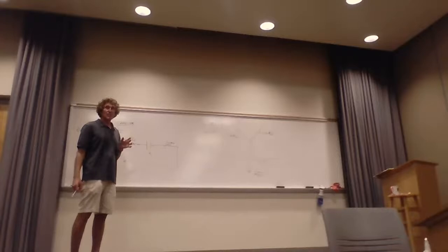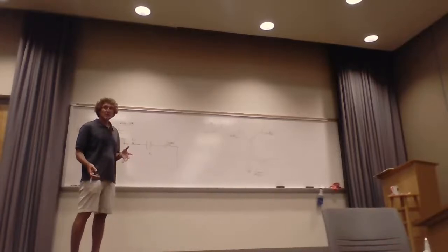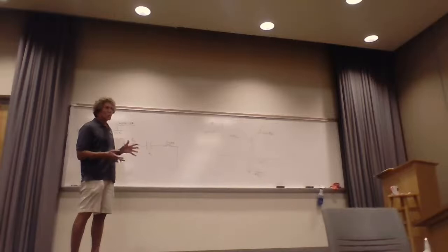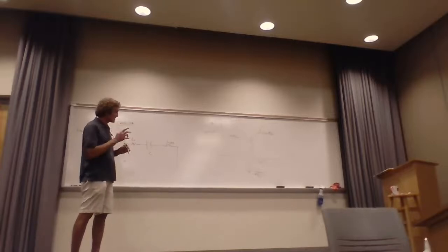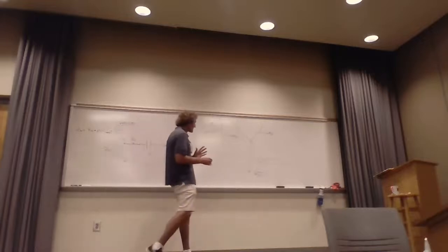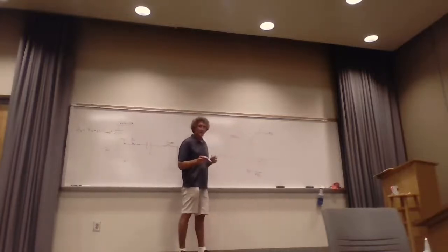They're not for high energy density capacitors or anything like that. You'll have to look at them from a manufacturer to see the best way to model. And I'll tell you this much, it's good to know some basics about this for one reason. Most of the time, this self-resonant frequency is very easy to calculate, and you don't want to operate anything near it. At least, if possible, an order of magnitude less in frequency.